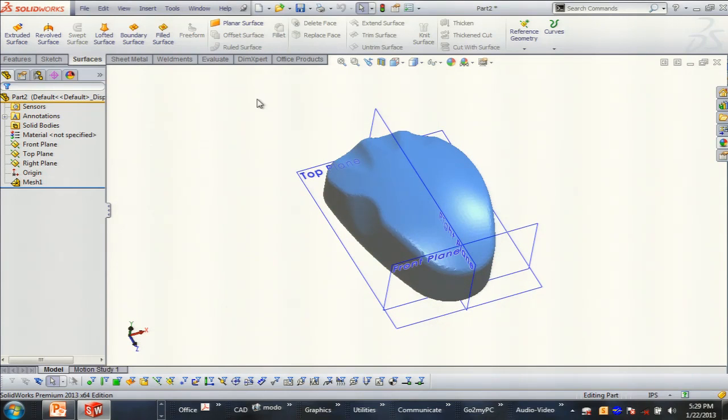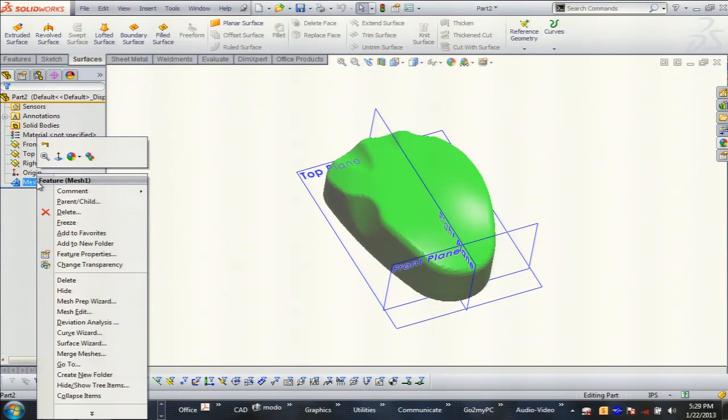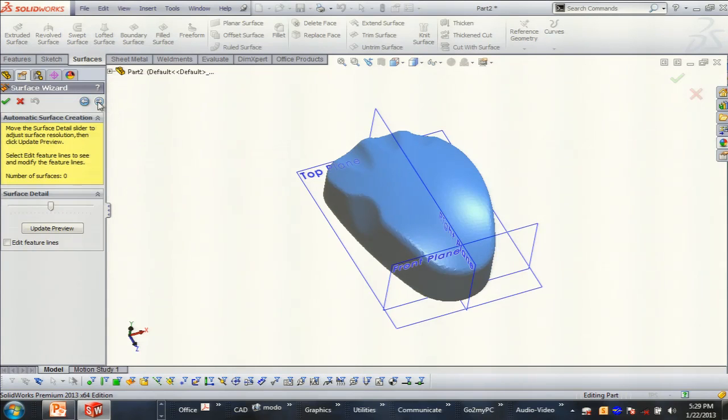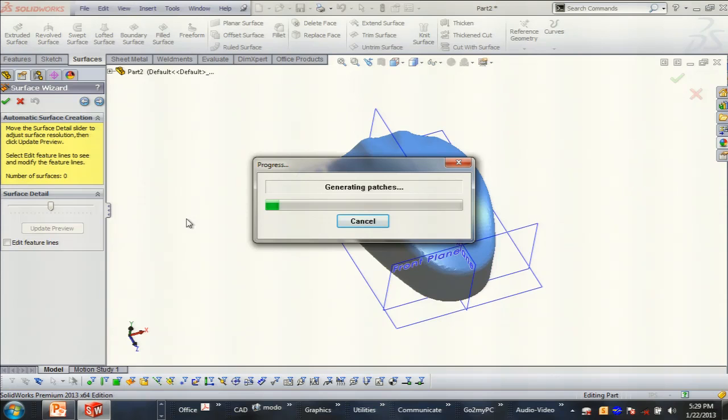And at this point, I have to make that decision. What am I going to do with it? Okay? So what if I wanted to do automatic extraction? Maybe I didn't come to this presentation, and automatic sounds good to me. I'm just going to make an automatic surface, okay? And thankfully, I got them to change this. We didn't make it the default, okay? I think guided extraction is more the default. But if you click on automatic, let's give that a try and see what happens. Okay, so now we're going to generate those surface patches. I think you'll get a feel for why this tool doesn't work for product design.